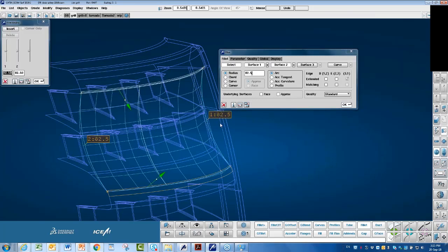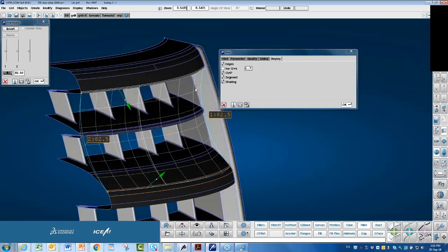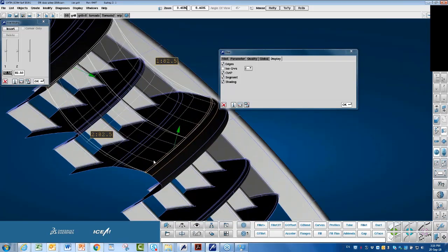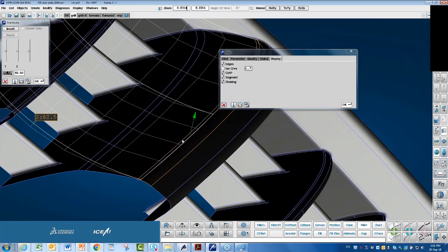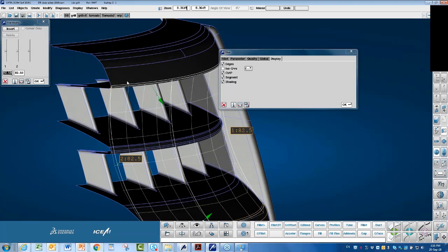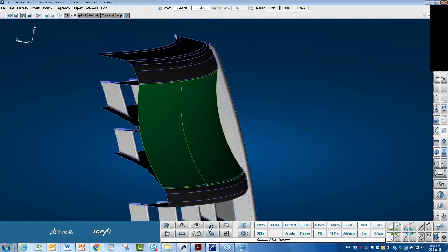So that is effectively the fillet that is being made by the analysis automatically. Then what we could do is extract these tan lines and use them for building geometry or for marking on the model where we wanted to be concerned with. I'll delete those.